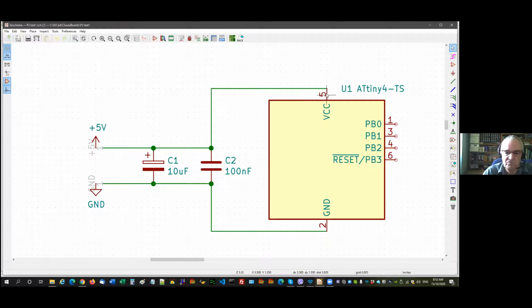You try and squeeze it right at particularly the VCC pin, usually because you've got a big ground plane. It's less important to have this pin close to here, although you want it as close as possible. But this pin here wants to be right on at this pin, if at all possible, because that's what's going to bypass the noise. So when this chip switches, when all the MOSFETs all switch, they generate noise and they generate high frequency. You know, classically 10 or more times the fundamental switching frequency.